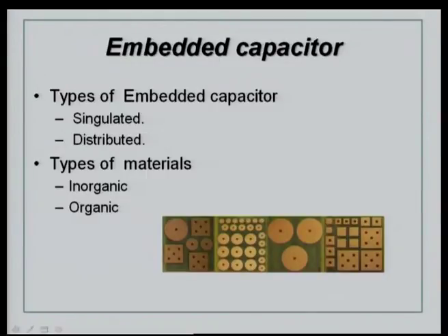As you know, in the plated through hole capacitors, the materials are fabricated by thick film technology, and the same is the case with SMD capacitors. So, they are actually co-fired and trimmed to the required tolerances that you require, and the good part of using these devices is that today you have equipment that can handle miniaturized surface mount capacitors.